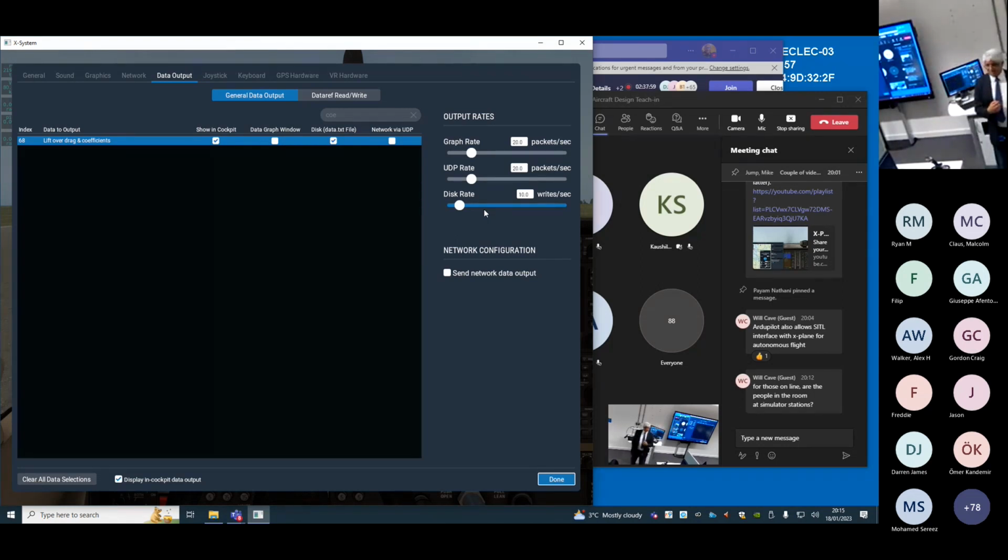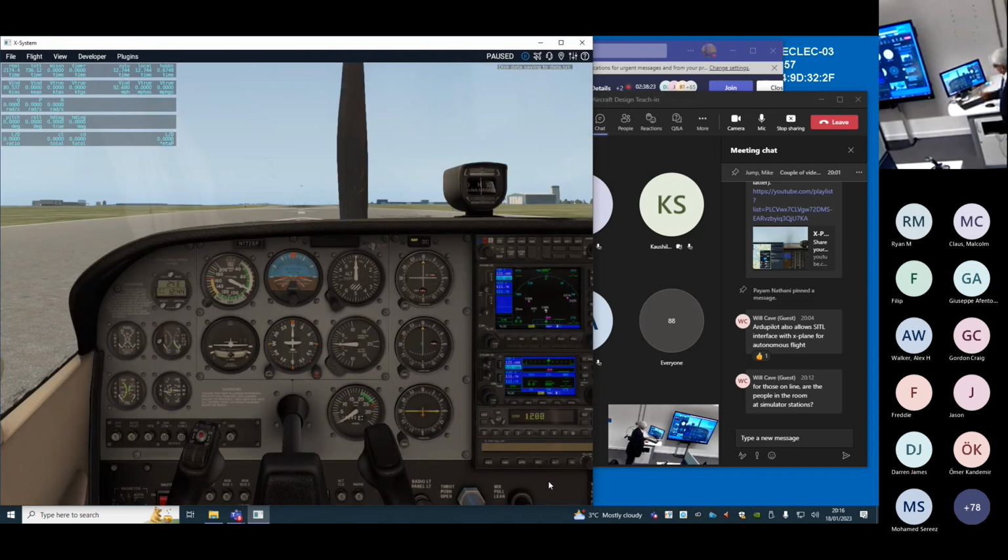Whereas if you're looking at the long-term mode, such as the phugoid, then 2 samples per second is adequate, because that's a mode that's going to persist in time for well over 60 seconds or more. That will be enough data for you to chart properly. So 10 hertz is adequate for my purposes for now, so we're going to leave this untouched.